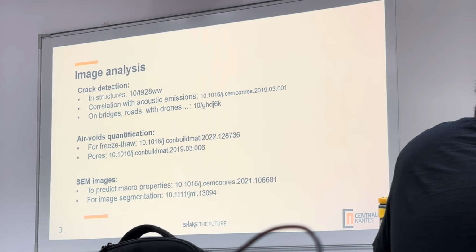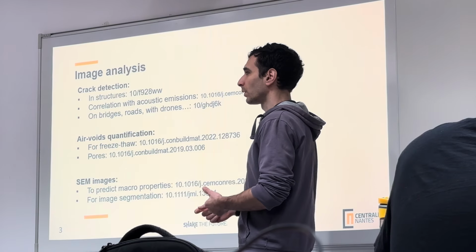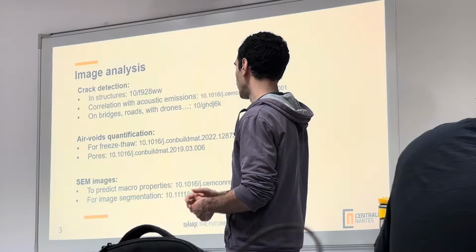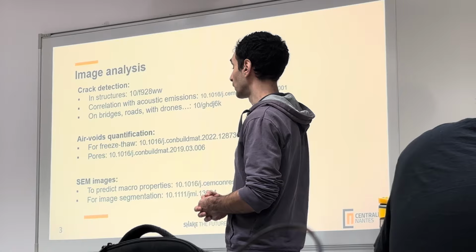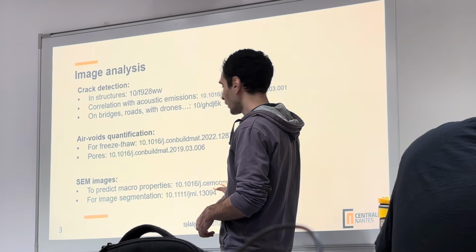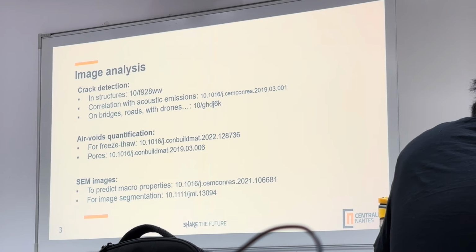And some people are doing SEM images, scanning electron microscope images, to predict macro properties, so they take images at small scale and they try to predict either durability or strength, or at least find all the phases in concrete.